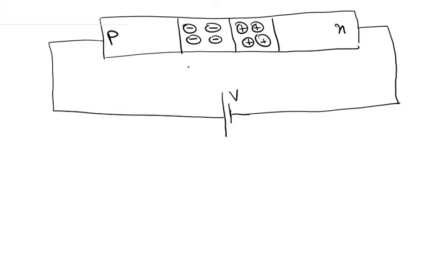So just as I discussed before, exactly at the PN junction, the main component of the current is the diffusion current. The diffusion current increases exponentially with the applied voltage, or the rate of diffusion of electrons from the N side to the P side, and the rate of diffusion of holes from the P side to the N side, increases exponentially with the applied voltage, and that is why the current in forward bias actually increases exponentially with the applied voltage. This thing we already discussed earlier.